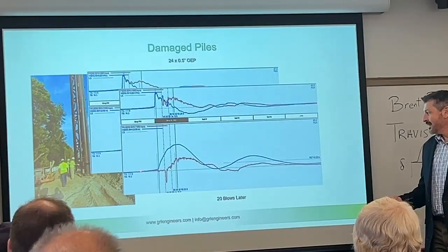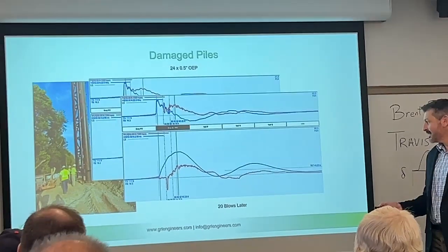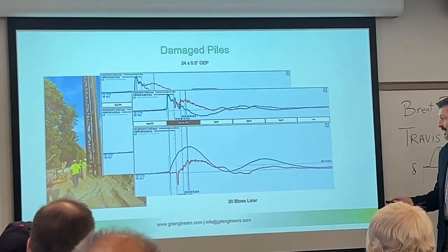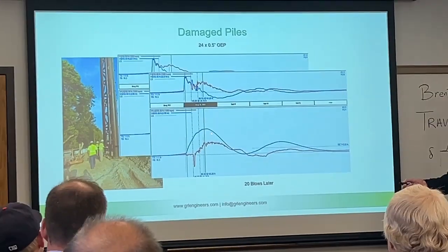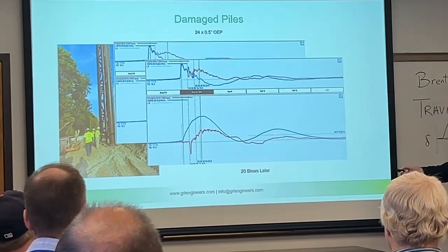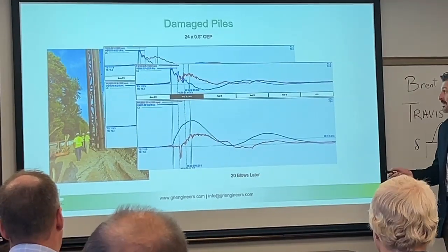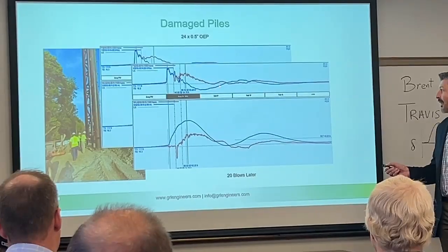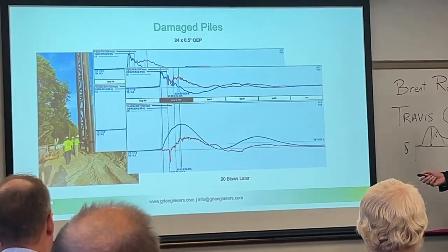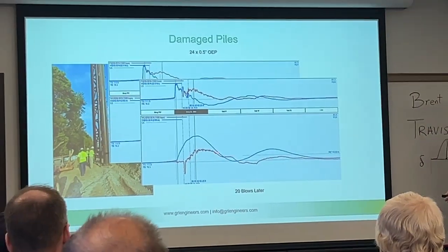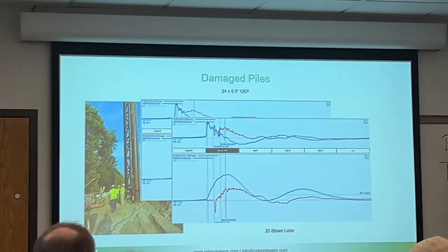So what comes after 2L over C, you're not just concerned about that? Oh, is that what you're talking about? Yeah. Well, the blue is the displacement on this lower one. You're asking about that blue trace? Well, maybe up above when they crisscross. Oh, when they're crisscrossing out here beyond 2L over C, that's an end-bearing response.